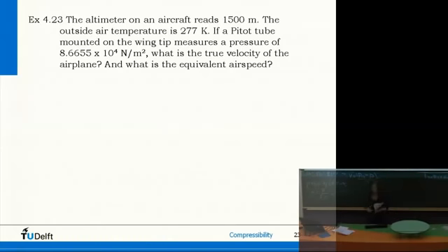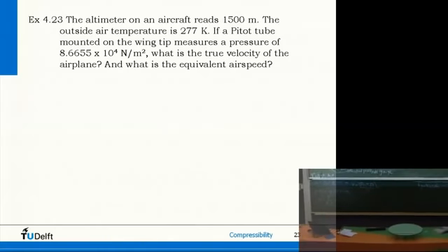So then, what pressure do we use, right? The strange thing is that the density we assume constant, the pressure changes a bit, so apparently the temperature also changes a bit, but we don't have information on how the temperature changes that bit, right? So what do we do? We have information on pressures at free stream conditions. So we use the temperature at free stream conditions. So we need the free stream pressure, P, so that's this one, at 1500 meters, at free stream conditions,